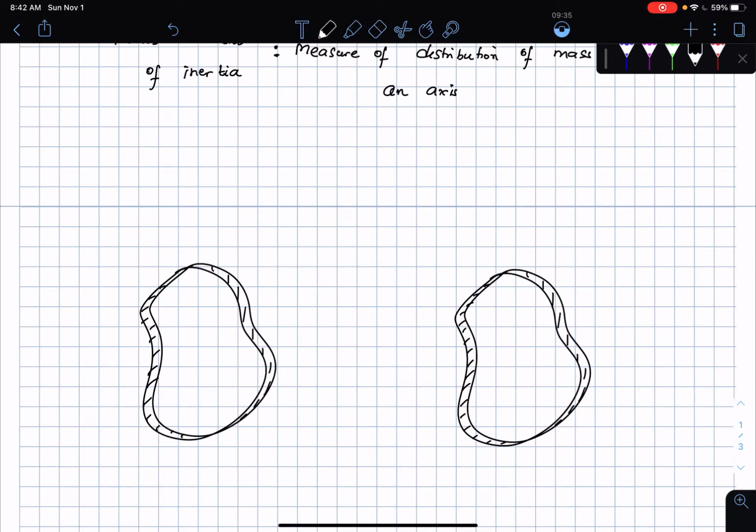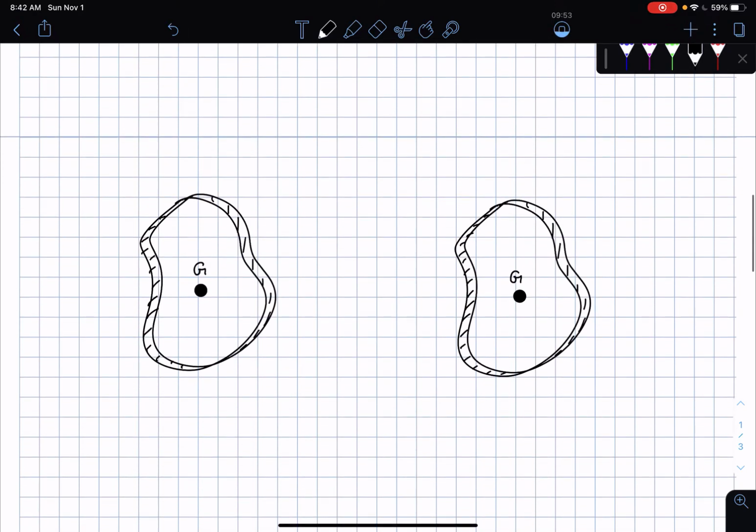Then here is typically what I do. I have the center of mass of the body, which is marked here. So I'm going to take that and copy that and put that down there as well. Okay, so that's the center of mass, which we will call the point G. So this is the point G. On the free body diagram, I'm going to have several forces acting on the body.